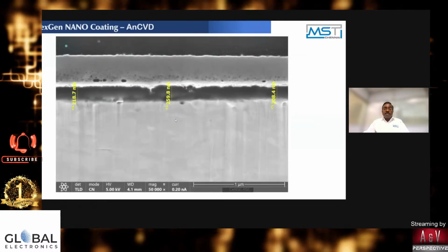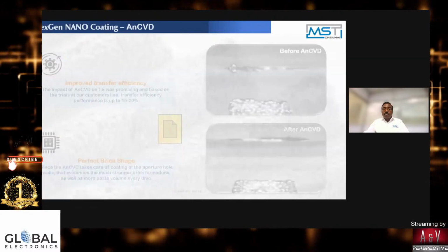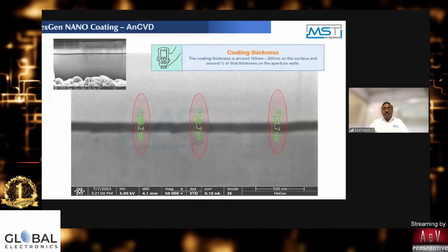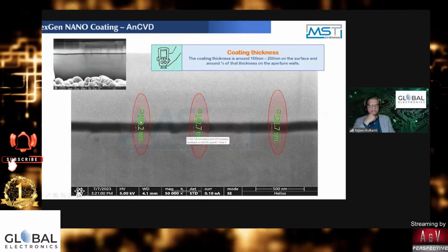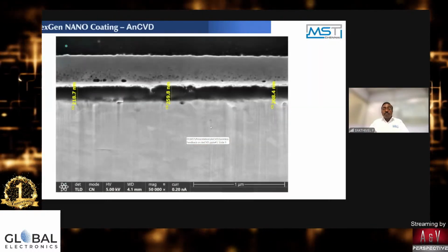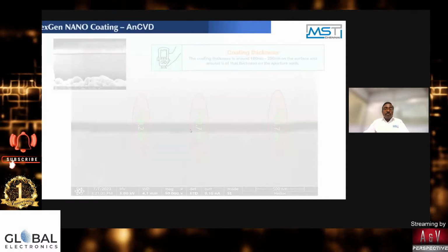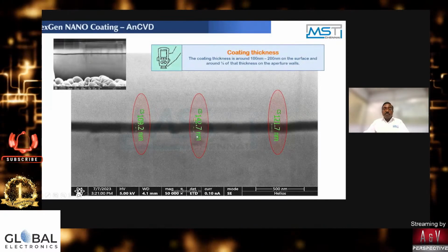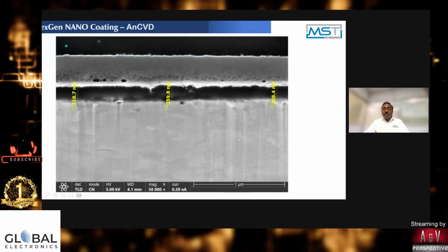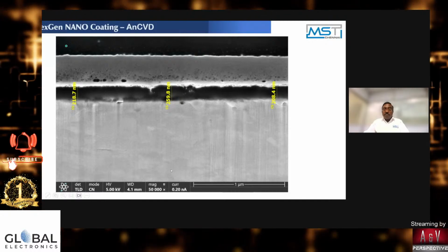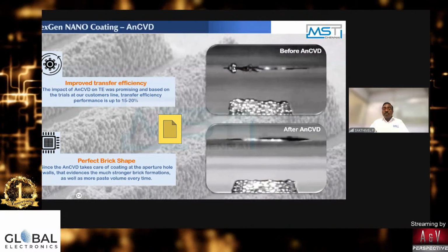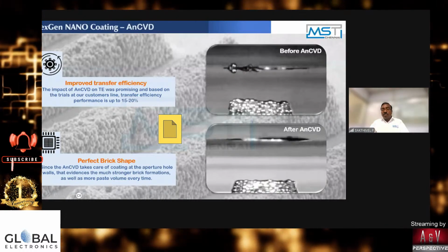See, this is the test report. Yes, very interesting technology. You see this test coating thickness measurement, 100 to 200 nanometers: 142, and another one, 259, 218, 259, 200. This was done last year. This is the evidence here. Before coating, the whole wall gets solder paste accumulated and dried.